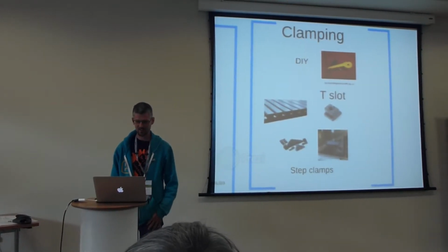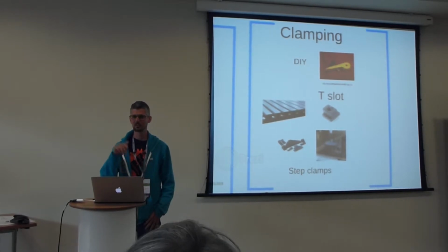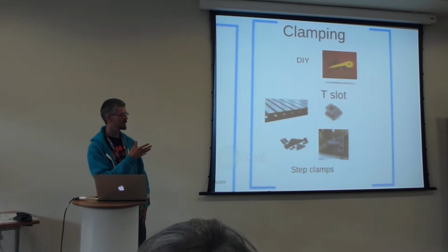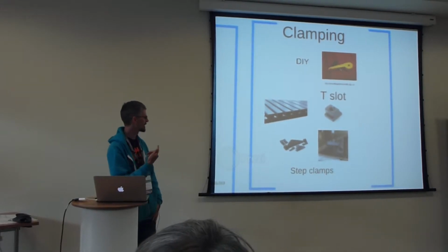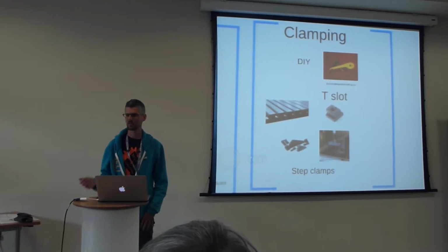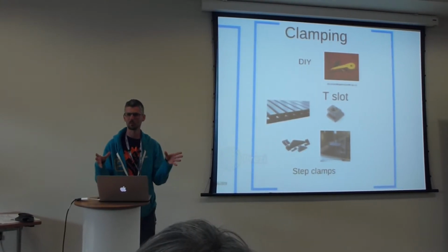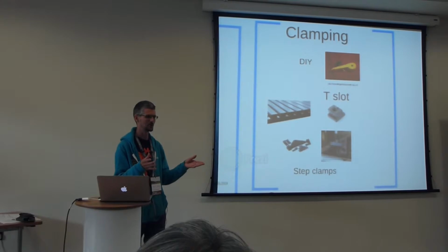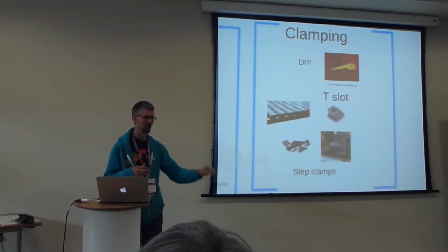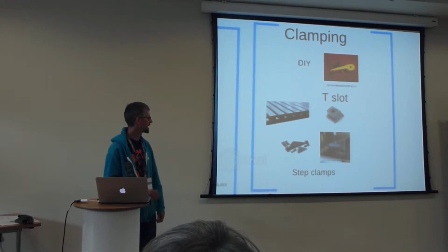One of the great things about a laser cutter is you can just slam your material in, close the lid, press go, and then 10 minutes later it's done. If you're milling and you're cutting, and especially with harder materials, stuff needs to be clamped down. I had a lot of accidents to start with where I've got like 90% through a 3-hour job, and then on the last cut the material moves and the whole thing is screwed up. So you really do need to clamp properly.